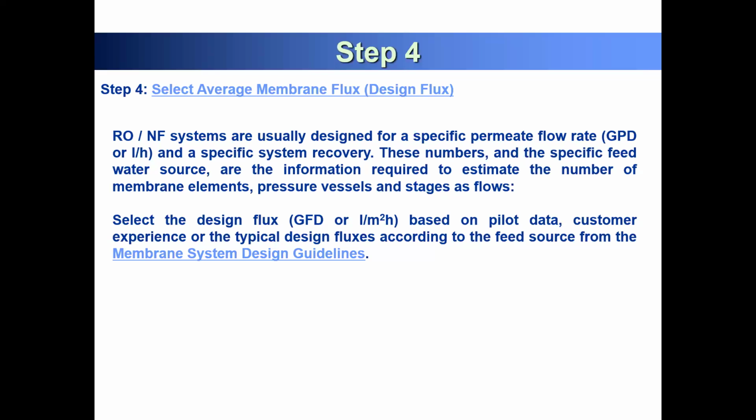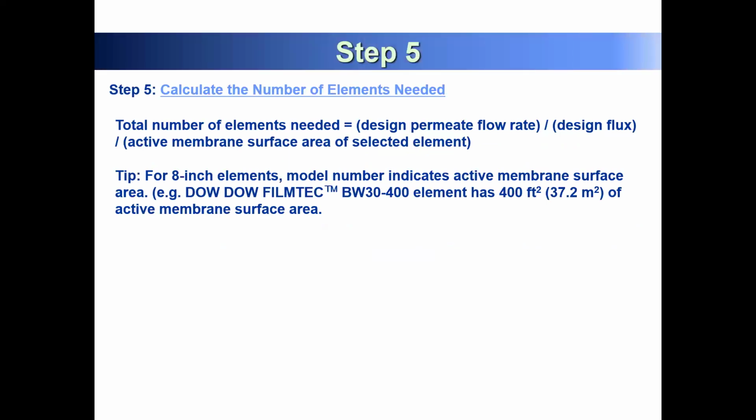So this is based on experience. Also, this company will provide basic information on what kind of average flux would be best. So let's say you recommend 30 LMH, or 40 LMH would be the best for your wastewater use purpose. And then we go to the next one.